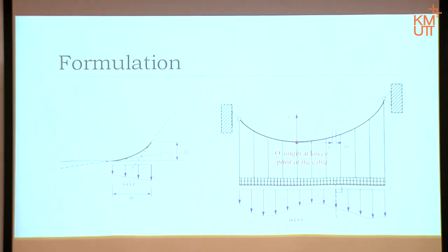The reason I have to draw the tangent line is that the axial force has to be on the same line as the member. It was quite easy to draw so far because our members tended to be straight lines, correct? This one here is not a straight line. So the tangent will be on the same line as the member at the cut point, and we have to rely on this tangent line, or the เส้นสัมผัส, to know the direction, right?